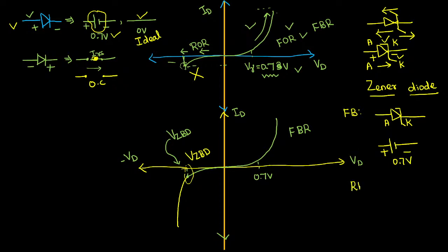When we are entering into the reverse bias region, what will happen? Almost it will be acting as an open circuit, but leakage current will be there. So there will be one more region, that is called the breakdown region. In reverse bias region, a very minor amount of leakage current will be flowing, but basically it will be behaving as an open circuit only. Minor leakage current means almost in nanoamperes, which is 10 power minus 9. Approximately that current will be 0.